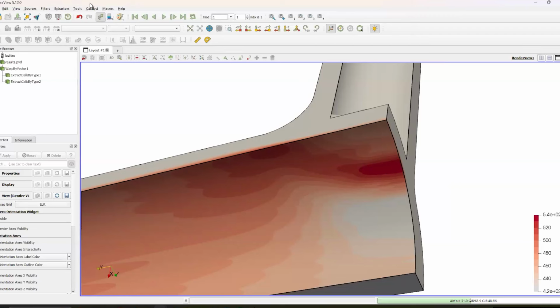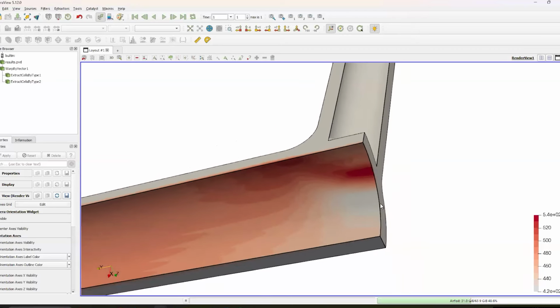You can see we're showing our results in ParaView. We currently export to a VTK format that's native to ParaView. We don't currently do any special post-processing of stresses. Many tools will do some volume-weighted averaging to remove what look like these mounds between element boundaries. We currently don't do any of that kind of post-processing, which is why it looks maybe a little bit odd out in the far field. But again, what matters is that we've weakly converged to our solution.